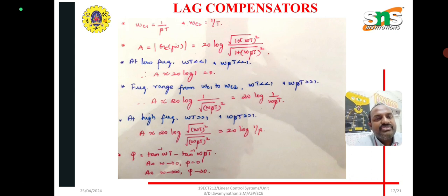So for the three different frequency ranges, just a reminder. The first one, at low frequency, it is 0. The third one, at high range of frequency, is 20 log 1 by beta. And the remaining one, between omega c1 and omega c2, is 20 log 1 divided by omega beta T. So these are the different gains.